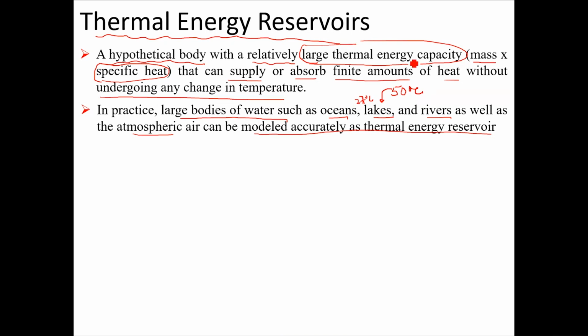It would not change. So the finite amount of heat that is being transferred to the lake would not cause any change in temperature of that thermal energy reservoir. So essentially, a reservoir is a body whose temperature remains unchanged if a certain amount of heat is being supplied by that body or absorbed by that body. And it is not necessary that this body is a very huge body. For example, you take your room.